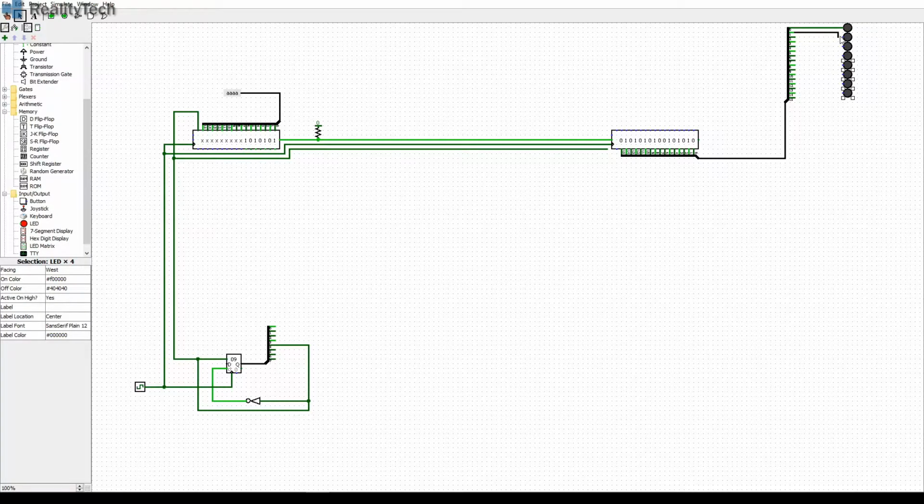You can immediately see as I start wiring these up, we've got a problem. Although we've got control of these LEDs, the LEDs follow the bits through the shift register, which isn't ideal. I mean, if you imagine these were the key switch lights on that number pad, that's really not going to be very useful.